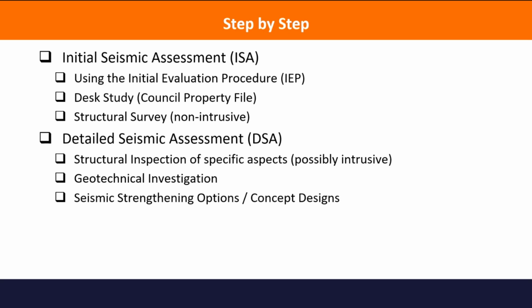Because unfortunately, in most buildings, the structure is hidden. It's hidden behind cladding, behind walls, behind ceilings. If you've got a modern office block with removable tiles, you don't have them here, but many office blocks have removable tiles, so it's easy to get into them. If you don't, you need to cut it out, which there's a cost to that and a cost to repair, which the client needs to be informed about.